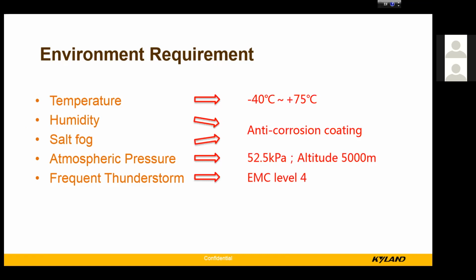And as you can see just now, the weather is very wet, and there is also some salt fog, which will cause damage to the PCB inside the switch. So we should apply an anti-corrosion coating on the PCB to avoid chemical corrosion.